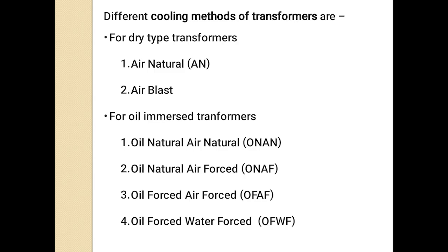This air natural transformer is otherwise called a self air cooled transformer, and this method of transformer cooling is generally used in smaller transformers, that is up to 3 MVA capacity. And in this method the transformer is allowed to cool by the natural air flow which is surrounding the transformer. So the second thing is the air blast transformer.